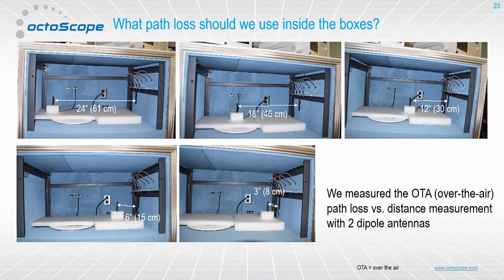I believe it does. What we're showing here is that the environment in the box is basically free space. We've damped down reflections, so we're not getting the effect of multipath from the box itself, and we don't have reflections from other elements in here. The environment is not cluttered, so we don't have clutter. Essentially, between any set of antennas, we're getting a free space model. To support MIMO, we would have, let's say, 4 antennas here and 4 antennas here, and between any pair of antennas, we're seeing free space propagation. Which is in fact the case.